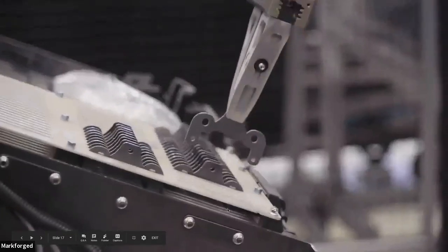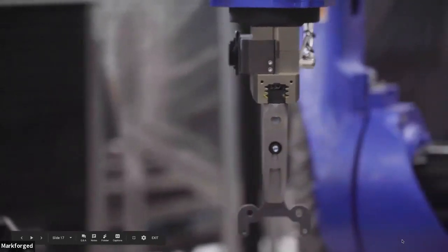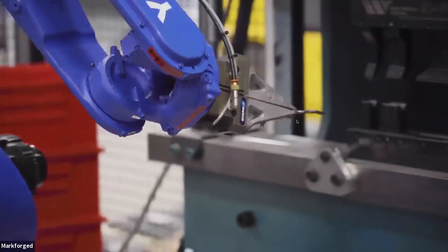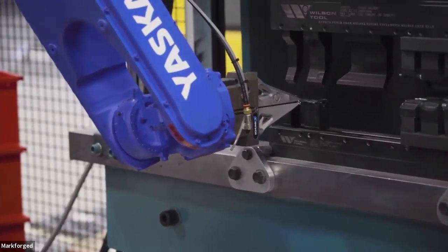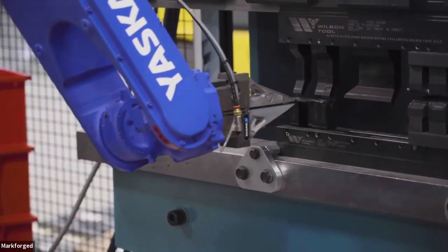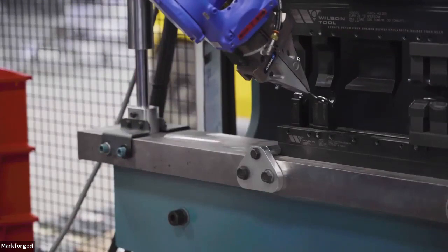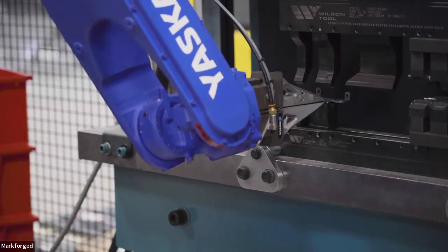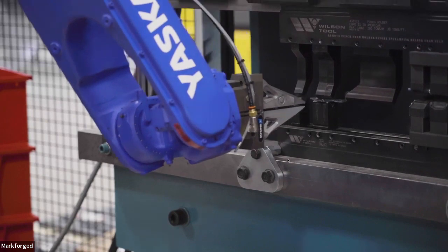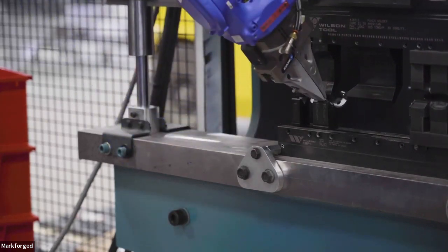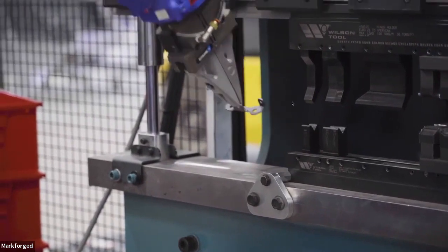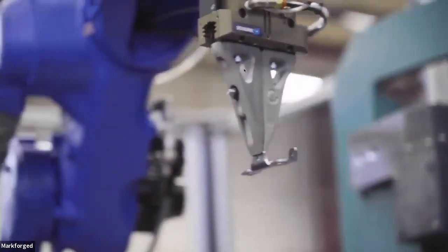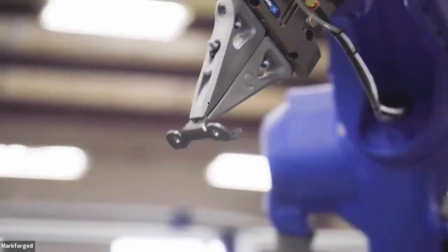The reason it is advantageous to 3D print these jaws is you can see that they have that taper where it's really thin on the area where it's gripping the part, and then it tapers. That's because, as you see during this operation, the part bends and it has to reach in and grip the part again without interfering with the tooling. This complex geometry would be really difficult to machine. It would be pretty time consuming, whereas you can just throw it on the metal 3D printer and do it without having to use your machine shop at all.